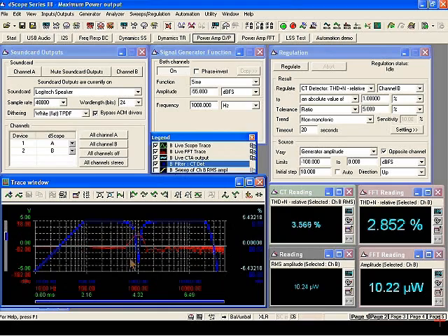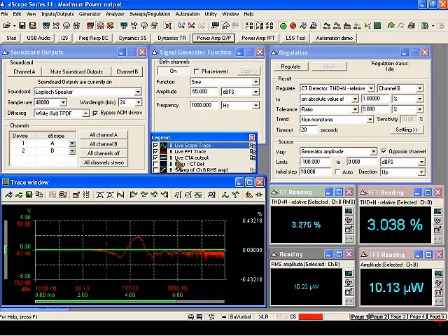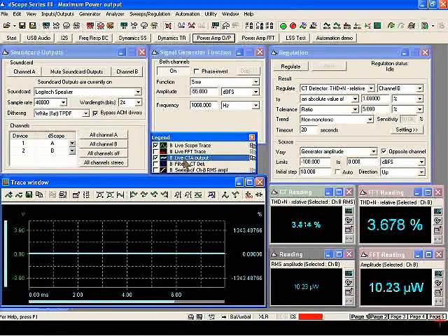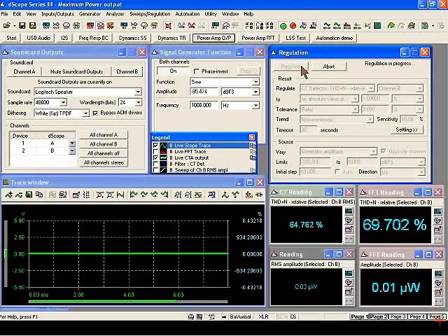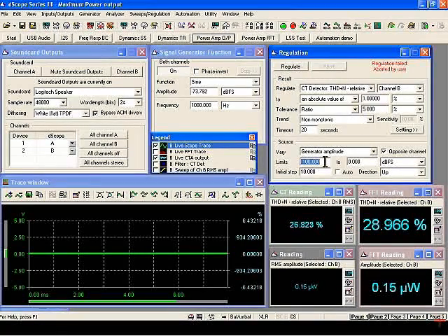So we're applying a 1 kHz notch filter in order to measure THD plus noise, and we can actually look at the time domain output from that filter in this light blue trace, and you will see when we start to reach the point of clipping, we will see harmonic distortion products appear in that residual waveform. So onwards, let's regulate. And I've just realised that I've started at a very low amplitude there, which is not what I wanted.